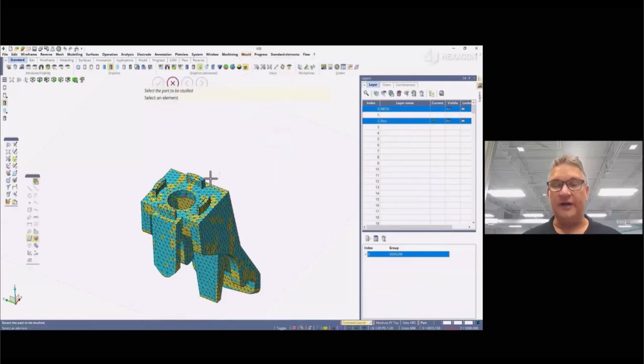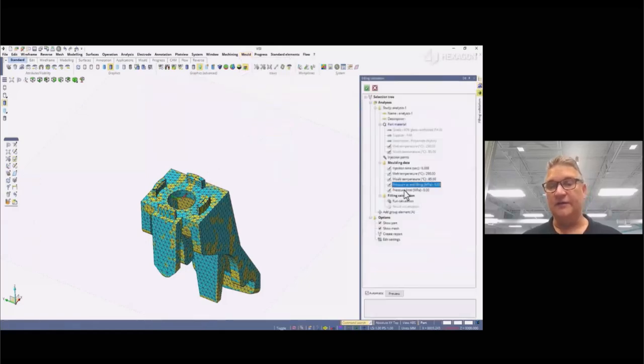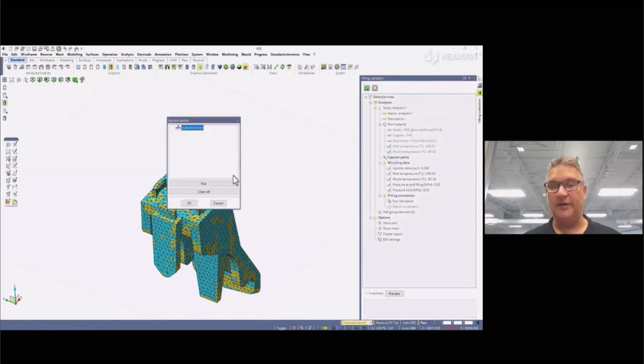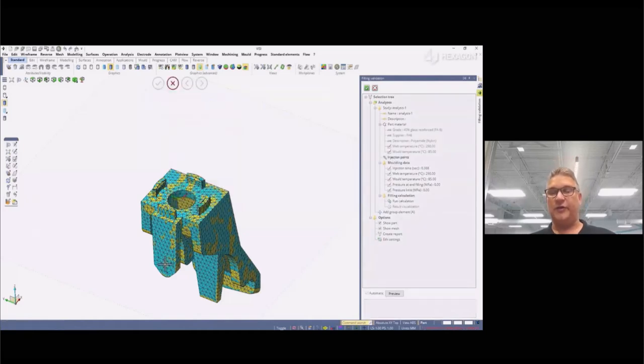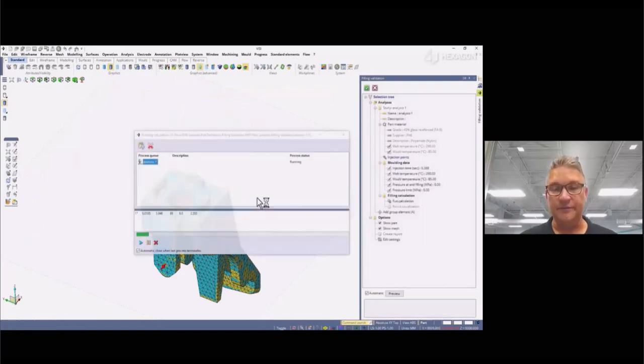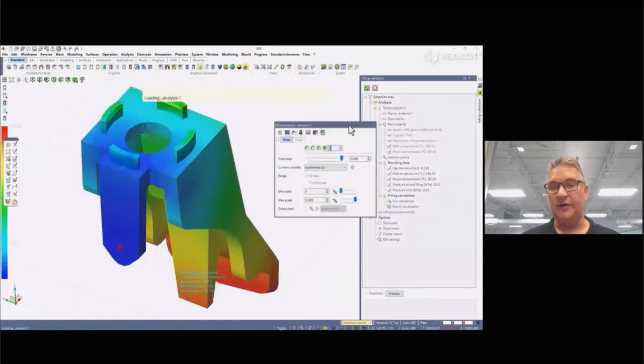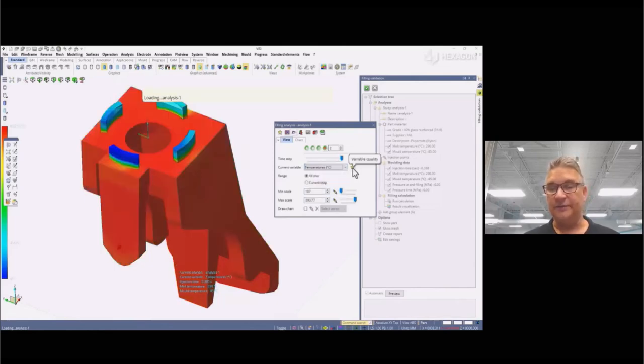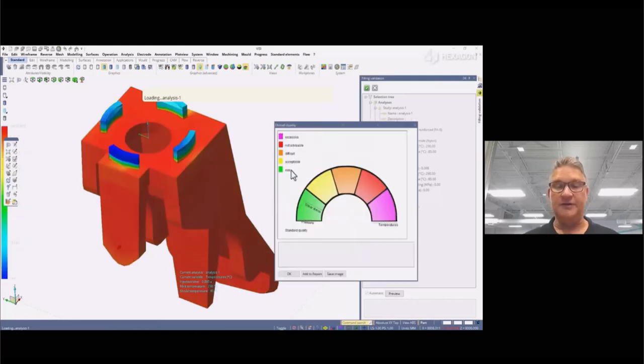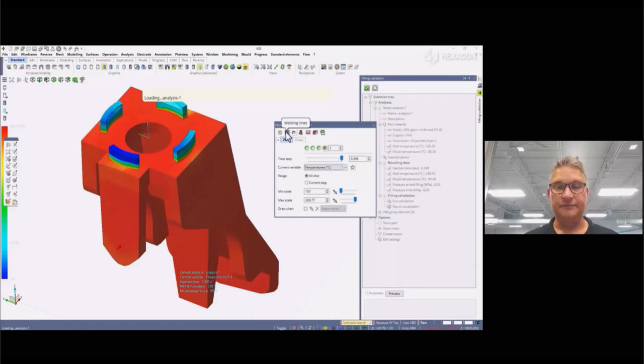Opening the filling validation command, we can see VISI shows the parameters for injection time, melt temp, mold temp, and others. Now let's pick an injection point and run the calculation. Once the calculation is done, we can view the results of different variables like isochrone, temperature, pressure, etc. Looking at the temperature settings in the filling analysis, we can view different quality templates to make some assumptions.